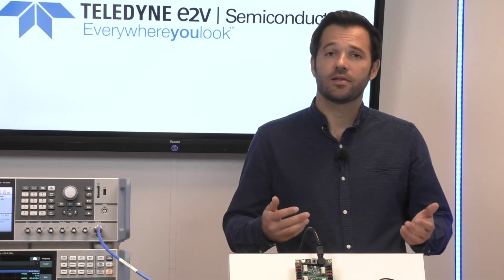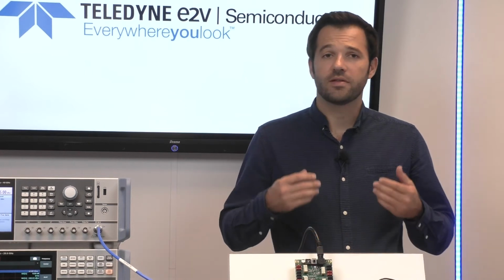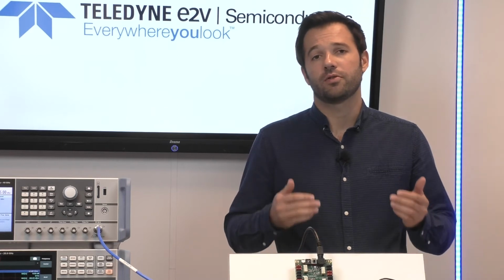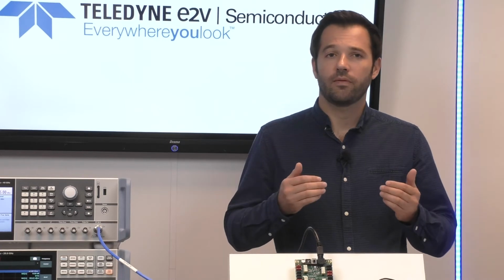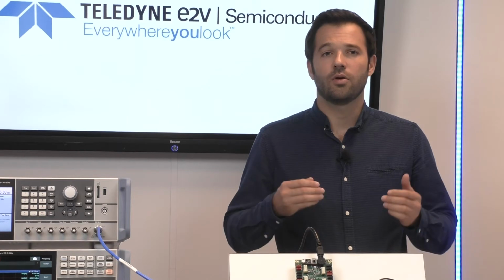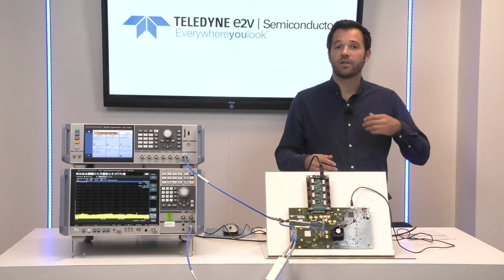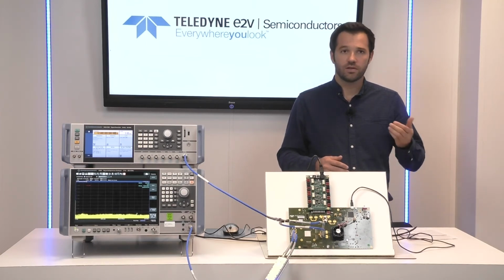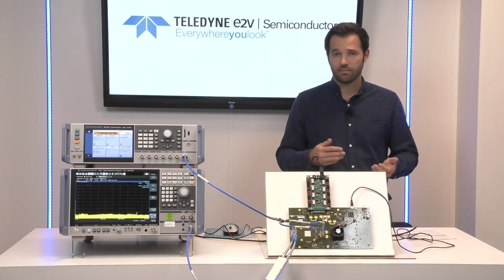Indeed, radars have different capabilities at different frequency bands. Lower frequency bands like P, L, and C bands offer better performance on penetration depth and on target detection. While with higher frequency bands like X, Ku, and Ka bands, it is easier to obtain accurate range and position measurements. So, there is a definite advantage in being able to develop a unique multiband SAR imaging system capable of generating signals in all these bands simultaneously.